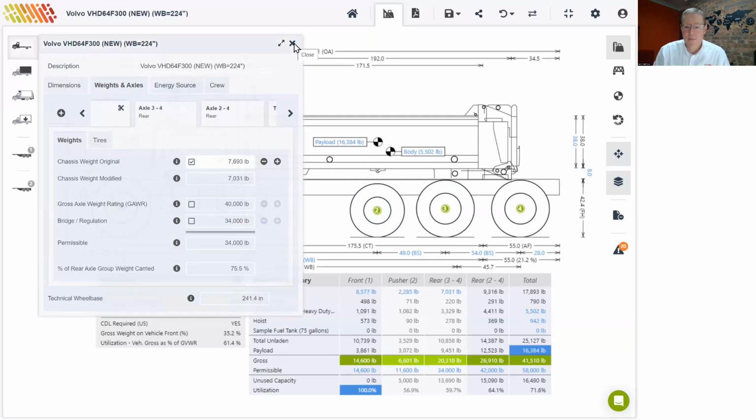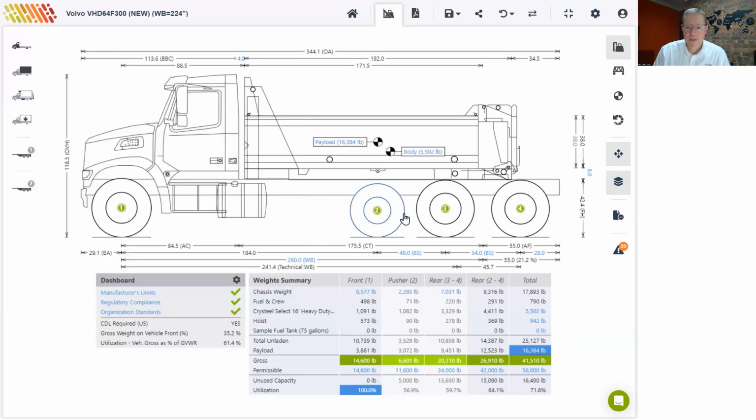Your chassis supplier can most probably give you more accurate values for the changes to the wheelbase. At this point, this is a little bit of an estimate, but roughly 200 to 300 pounds for the extra 3 feet of chassis length should be sufficient. And it is something that I checked with the manufacturer in this case too. They gave me a value of about 200 pounds for the extension.